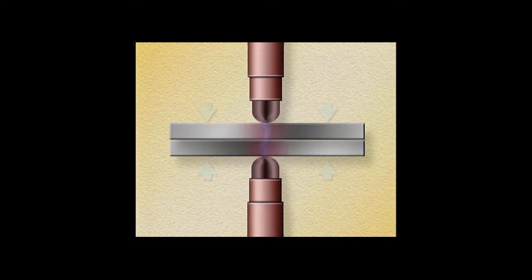In an extreme case of low force, resistance might actually be greater between the electrode and the part than between the parts being welded. This must be avoided because it can result in more heat being generated at the electrode tip than at the material faying surface. This could cause a surface expulsion, in which molten metal can be thrown off in any direction.